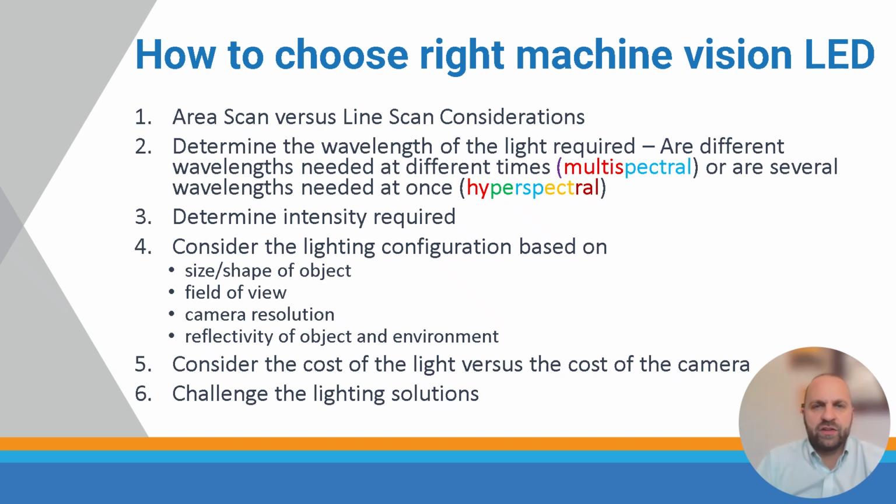We have another application note going into more when to consider line scan, but overall it's based on the size of the object, the complexity, shadowing, and what the complexity and the budget is for the project. With line scan, one thing, if the camera or the object is moving, that may be a hint that you might want to look at line scan as a consideration because you often need that movement to do a line scan application.